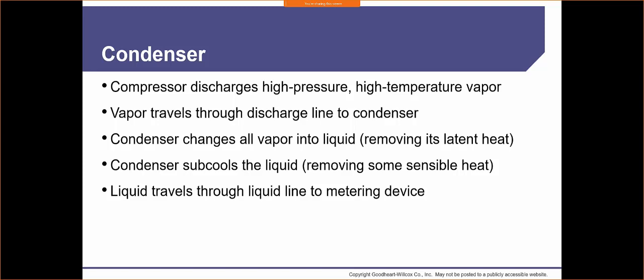If I have 110 degrees, I'm sorry, it would actually be below that, so it'd be 90 degrees. If I have 90 degrees, I have a 10-degree heat difference between the 100 and the 90. What that means is I would have to increase the temperature from 90 back to 100 to get to the point where I would turn into a vapor.